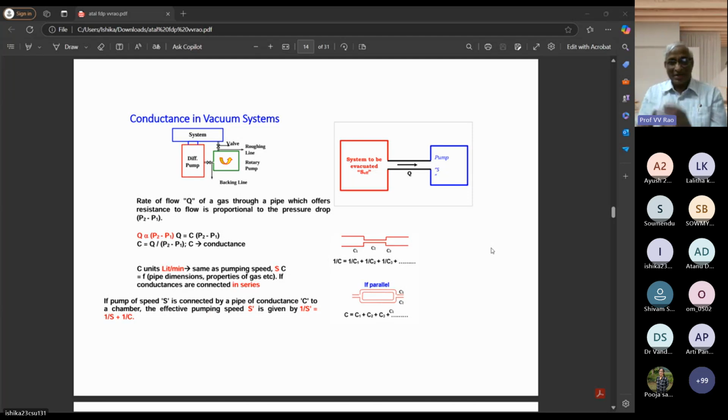So pumps have to be connected. But these pumps are relatively noisy, oily, and they have their own problems. It's not like a chamber. So you require a connecting pipe. And for convenience, it is often required to have a sufficiently flexible pipe, sufficiently long with some bends, so that the pump is a little bit away from the system, but is doing its duty of evacuation. And then we try to do evaporation, thin films, and etching in our own way. Depending on the particular operation, we isolate the remaining parts. This is what has been discussed in the last three sections for all of you.